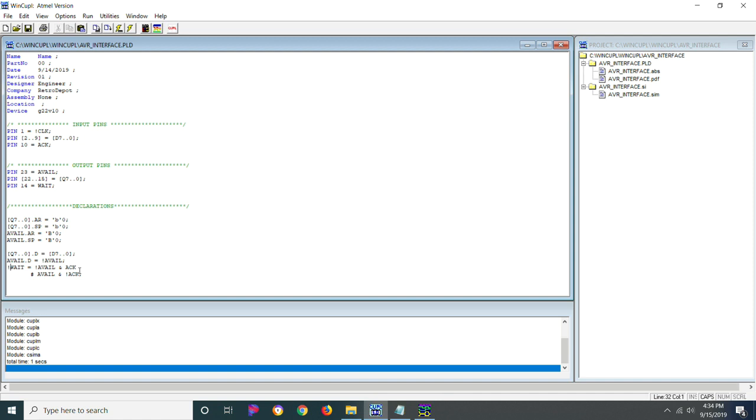Now, where this comes in handy is if you wanted to do, for example, memory banking, so that depending upon what bank was set, you could, for example, let's say that you took the top 3 address lines and you latched that data. For example, you latched a 6 into the registers. You could then feed the inputs back in and then read a 13, 14, and 15, and when the data matches, that's whenever it trips a particular chip select line. So it's just an easy way of doing it.